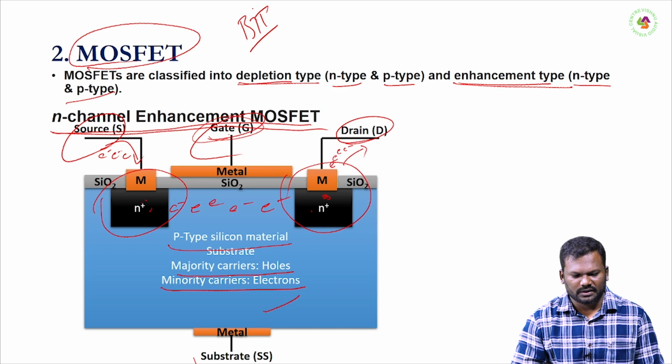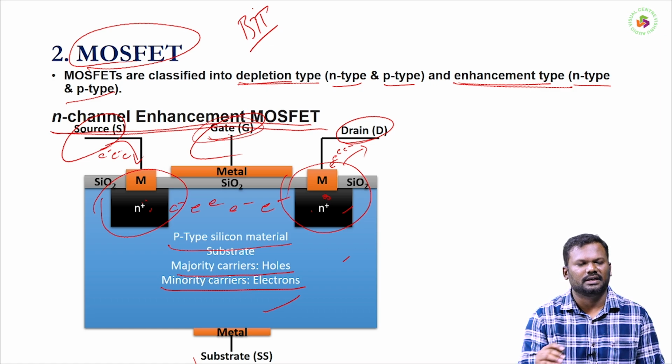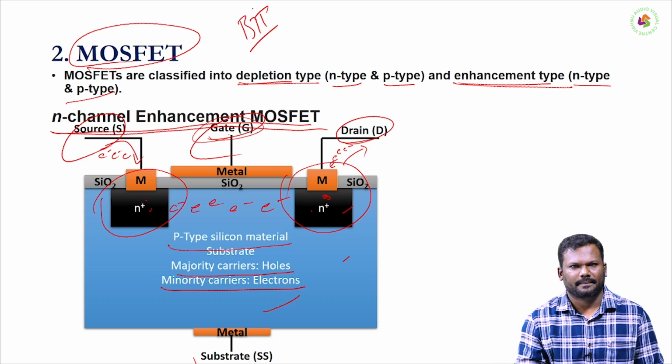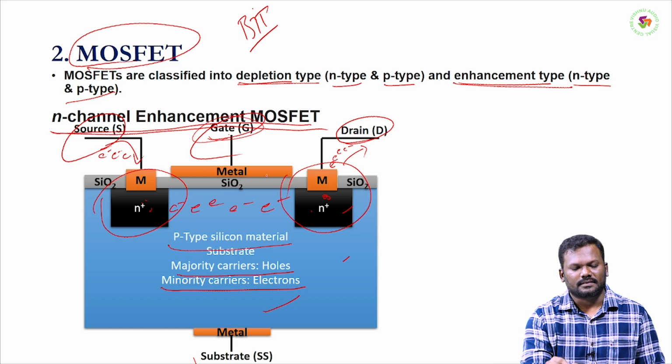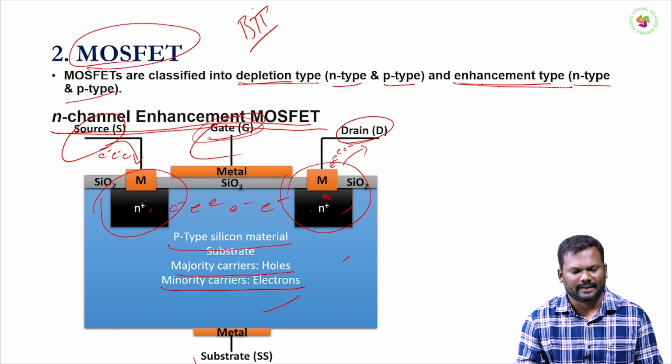So, the structure of MOSFET: first, select a p-type substrate, then diffuse the N regions, both N regions, which we call the source and drain regions. Now deposit silicon dioxide, and on top of it you deposit metals. The metals act like contacts.